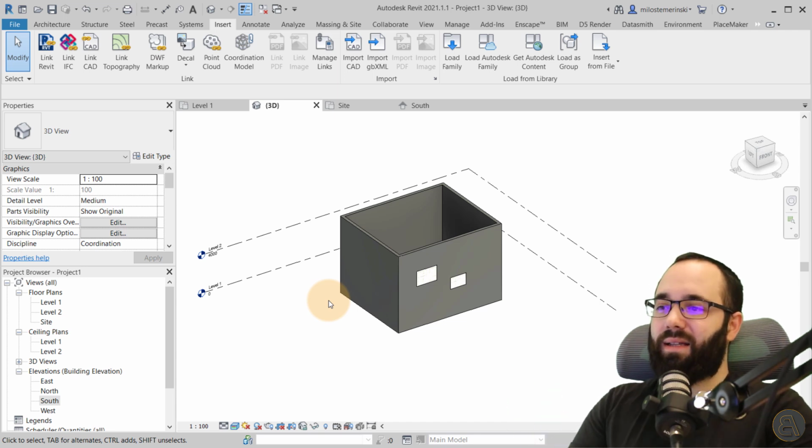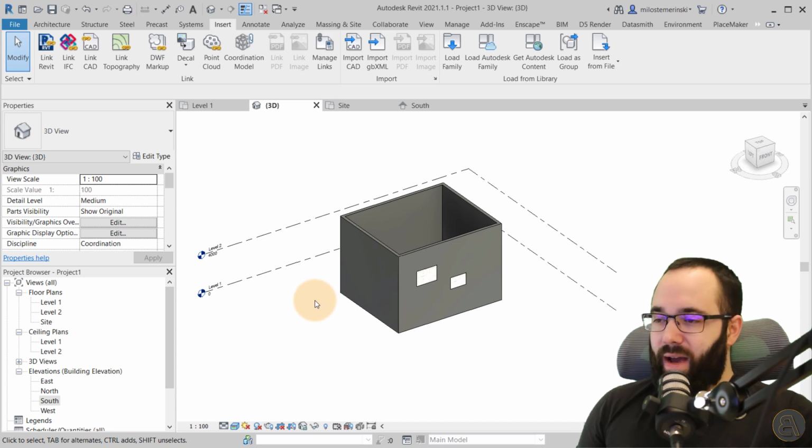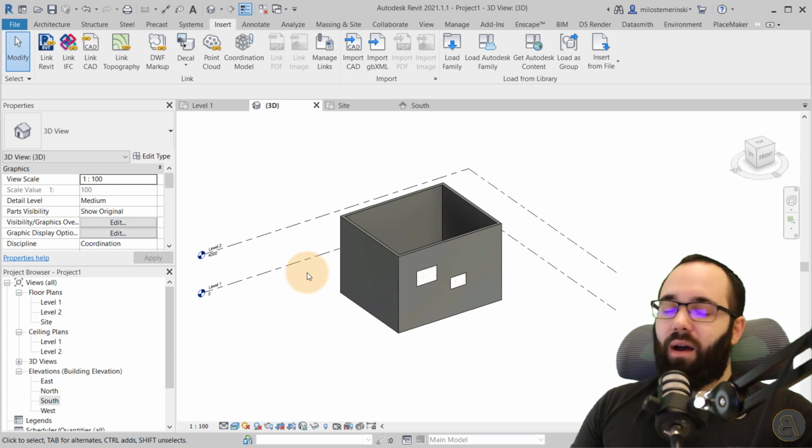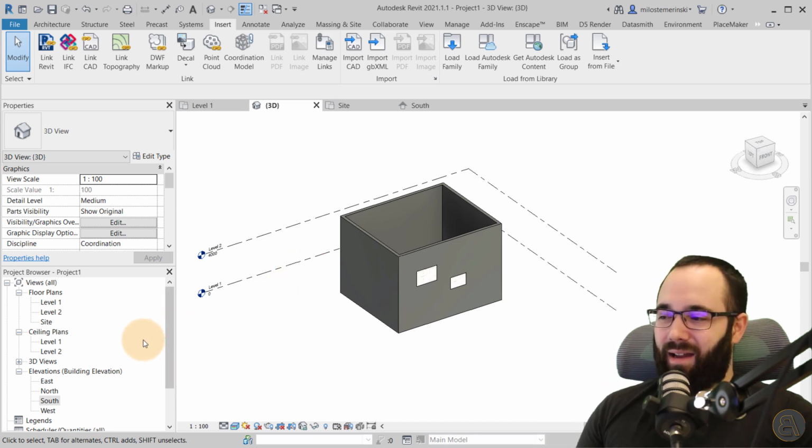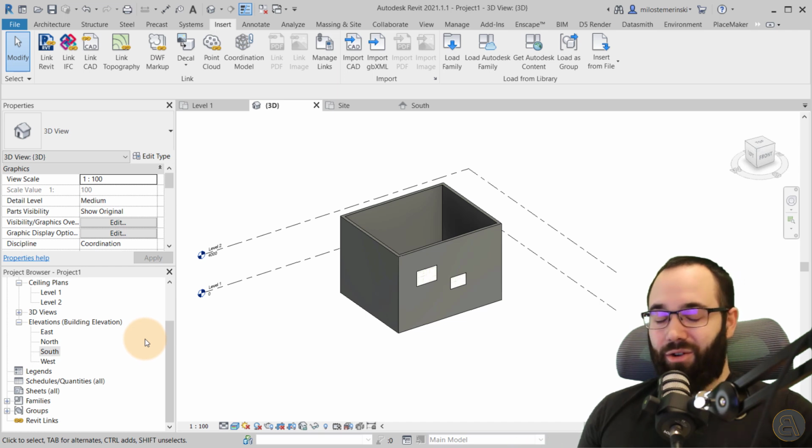I think it's a quick way of exporting views. So to export views as images, obviously don't do this for completed panels and for your sheets and so on, but for just quick views, just to play around, perhaps draw over it, I think exporting as images is a really good solution.